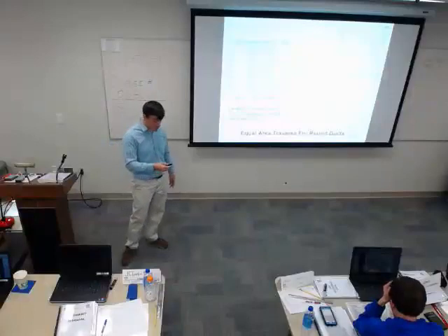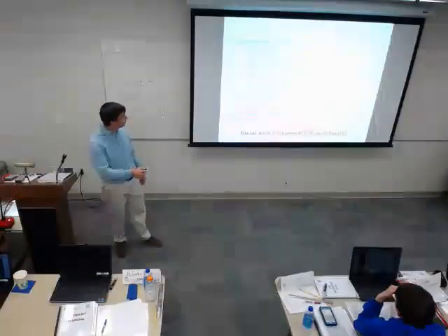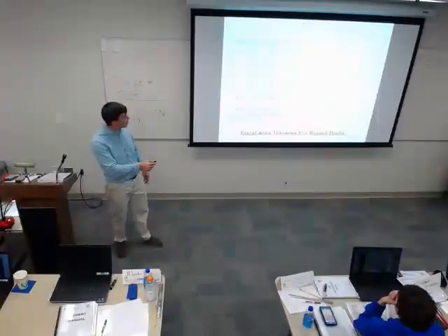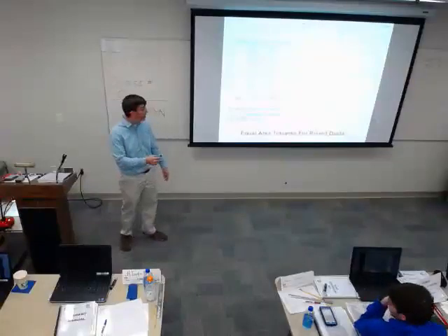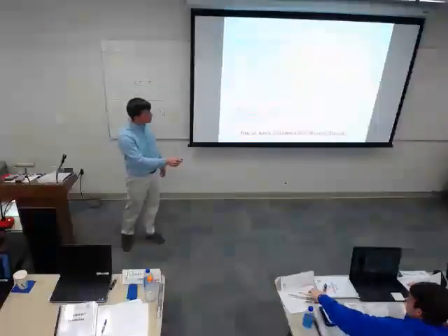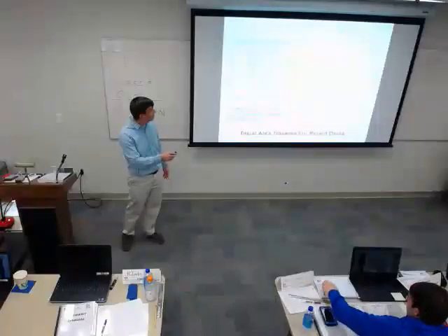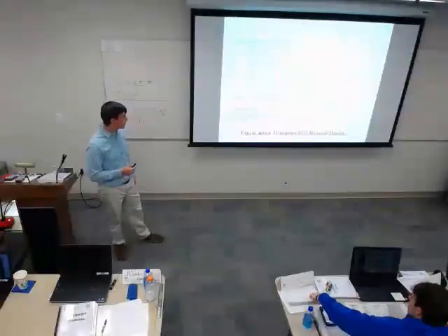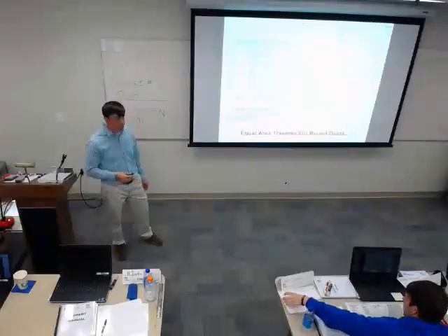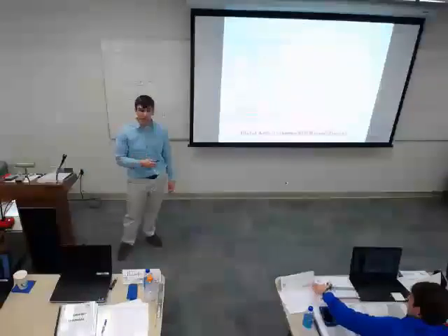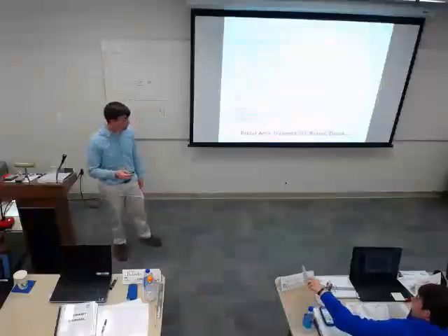Basically the same thing for a round duct. The point being, how many measurements do I need to have and where are they, depending on which size duct you have. You'll notice he's not supposed to take one in the center for the standard. The standard tells him how far apart your readings are. You'd have no way of knowing if he did it per that, if you don't get each individual reading, how he laid that grid out.